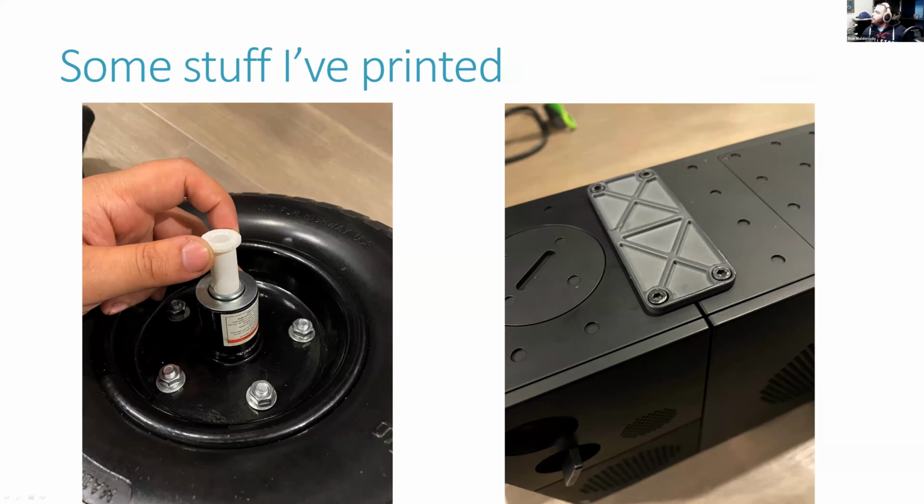Dan, I think this one from Kent might be better suited to you. What is the resolution tolerance on the printer? No problem. Great question, Kent. It's an interesting question. People often ask about resolution with 3D printers. That's not really an applicable term with SLA printing, especially the way Formlabs does it. But basically, it comes down to layer height, which is the Z dimension of accuracy, and the X and Y. The X and Y is, I think, between 100 and 120 microns across. It's essentially the width of the laser beam that's doing the curing. That's your XY parameter.